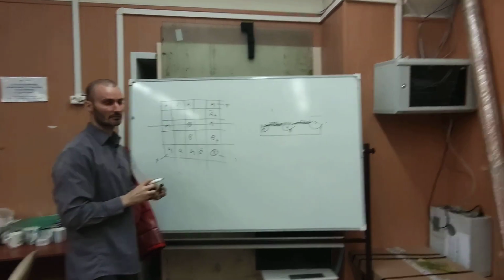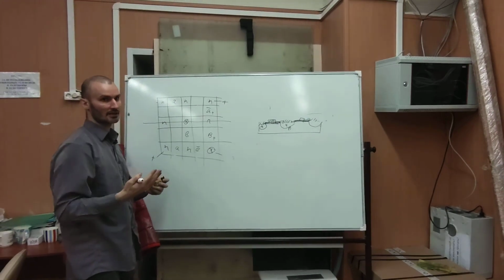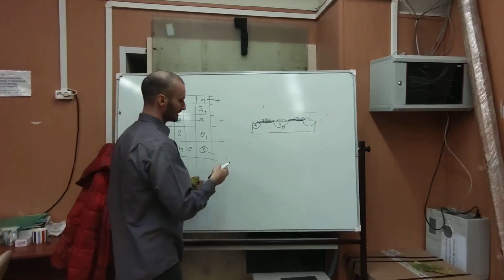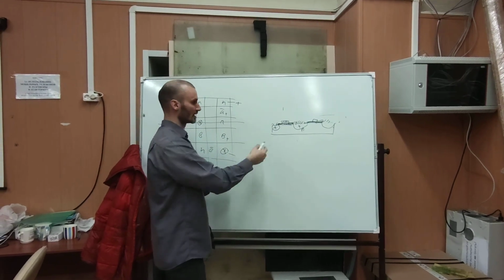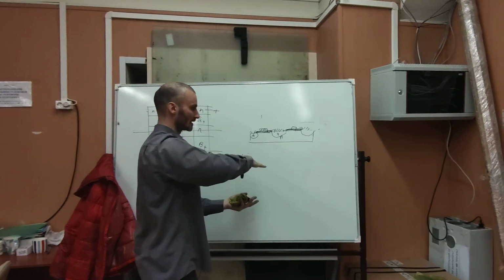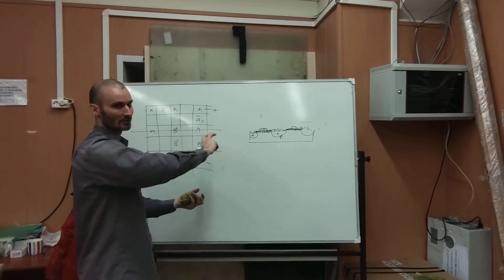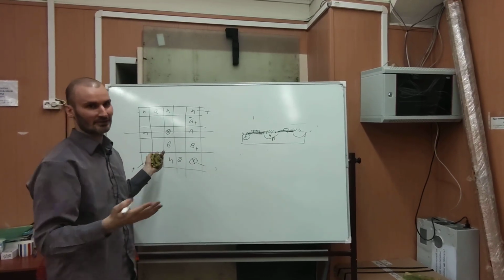We will order from JLC PCB the circuit cell. We will design it in easy EDA. Then we will apply solder paste to the points of that circuit. We will reverse it and place on top, heat it, and solder will connect all the pieces together. And that will be our final product.